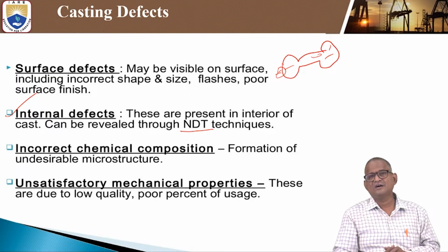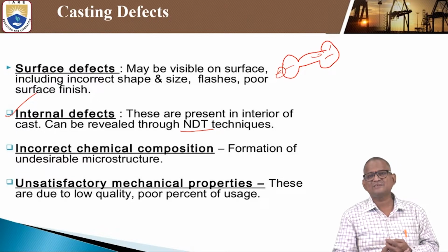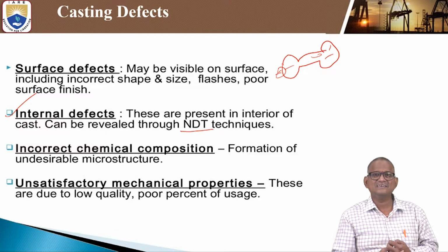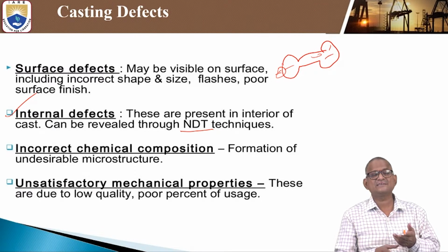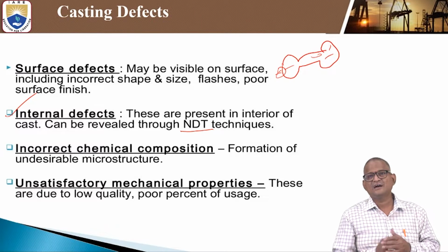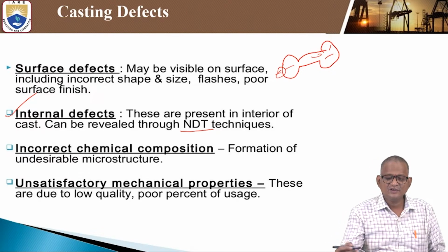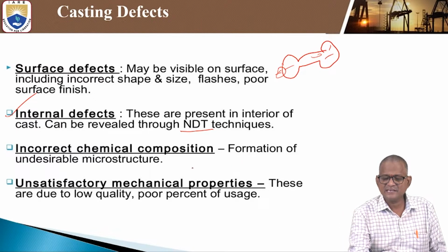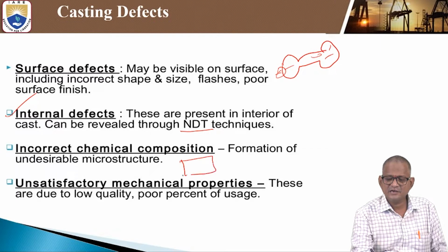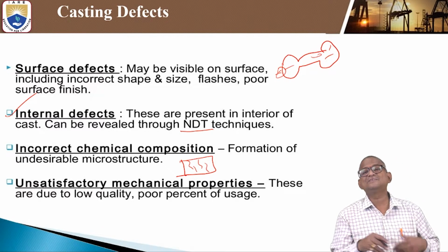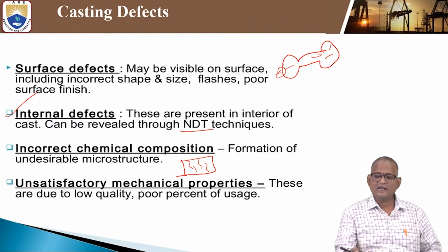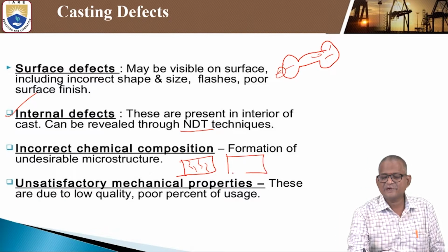Even whatever product is made from this casting process, initially they can check if it is a cast iron. Again, there are different types of cast iron: grey cast iron, SG iron (spheroid graphite cast iron), malleable cast iron, and white cast iron. Coming to the grey cast iron, look at the structure, you can see some flakes formed. If the flakes are not there, then obviously it says there is a mixing of the grey cast iron. And suppose it is SG iron, spheroid graphite.